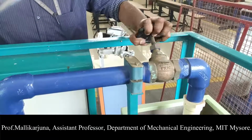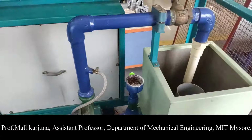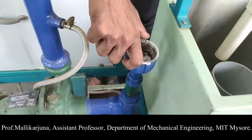In order to control the flow rate, we can open this so that we can control the delivery from the pump. And then here one small opening is given. This opening is provided in order to avoid the priming problem.